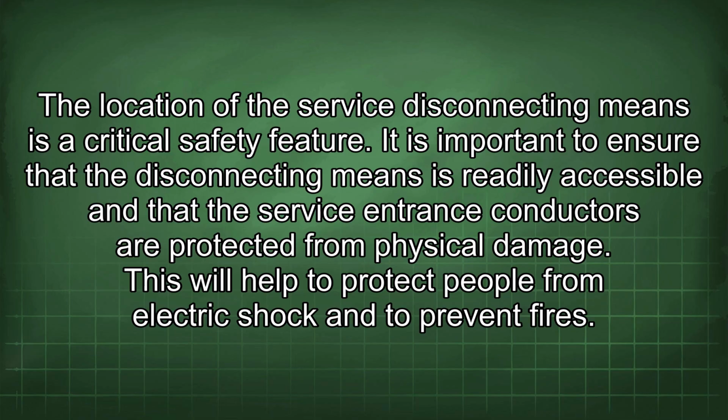The location of the service disconnecting means is a critical safety feature. It is important to ensure that the disconnecting means is readily accessible and that the service entrance conductors are protected from physical damage. This will help to protect people from electric shock and to prevent fires.